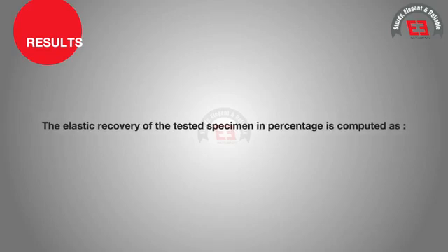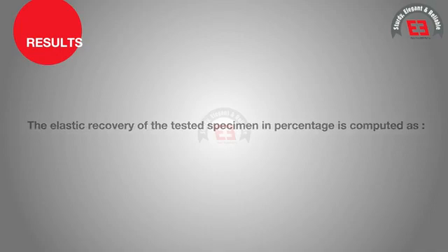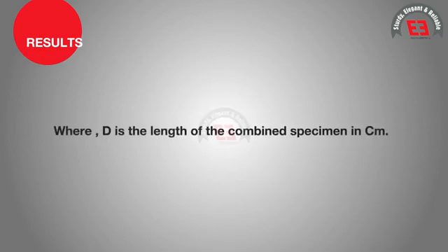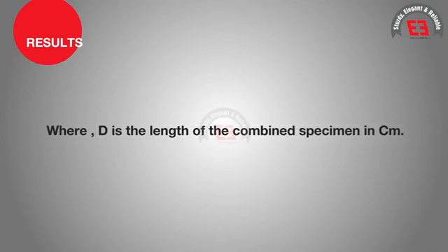Results: the elastic recovery of the tested specimen in percentage is computed as elastic recovery percentage equals 100 times (10 minus d) upon 10, where d is the length of the combined specimen in centimeters.